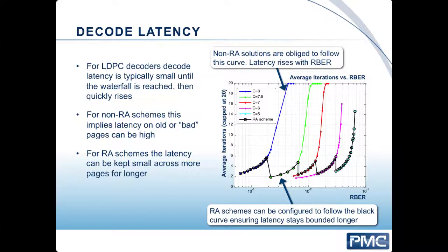Read latency is a very important metric for a solid-state drive. If we can minimize the read latency, we can ensure that experiences for the users are maximized. In the graph on this slide, we plot the latency associated with LDPC coding for different rates of code. In a single rate scheme, what would happen is that the latency observed by the user would increase as the drive aged. So your gaming experience on an older SSD would be worse than it would on a new SSD, which would force you to go and buy a new solid-state drive much more often in order to maintain a maximal user experience.